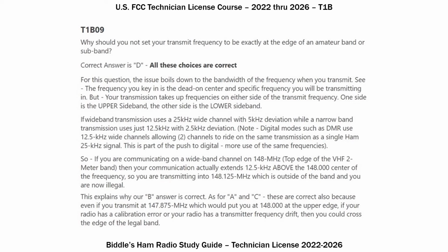On one side is the upper sideband, the other side is the lower sideband. A wideband transmission uses a 25 kilohertz wide channel with 5 kilohertz deviation, while a narrowband transmission uses just 12.5 kilohertz with a 2.5 kilohertz deviation.